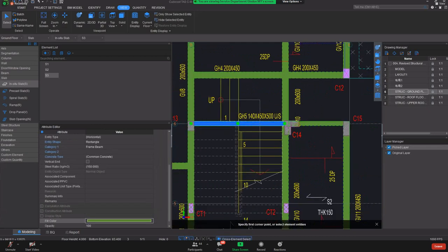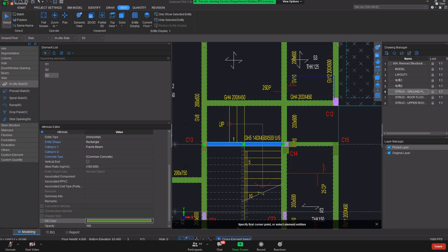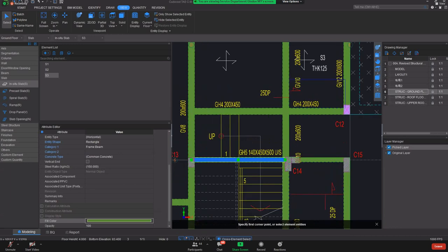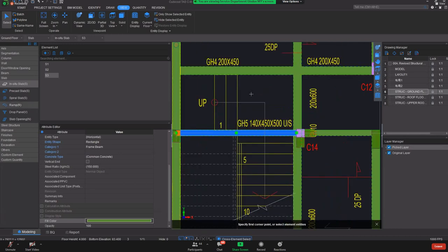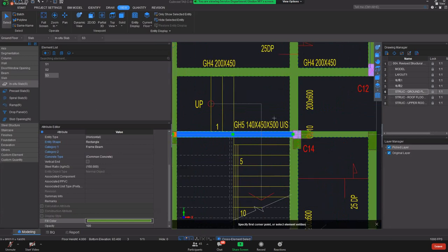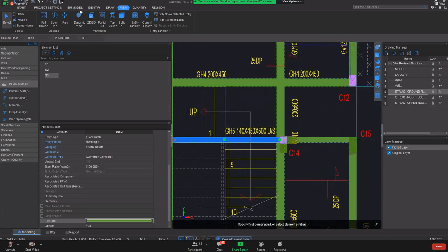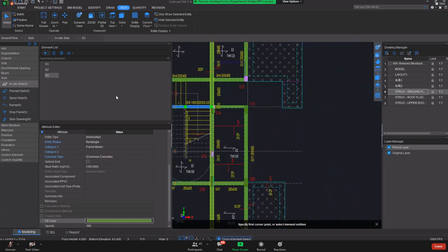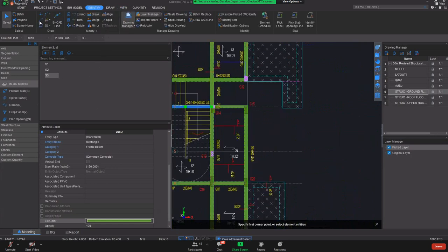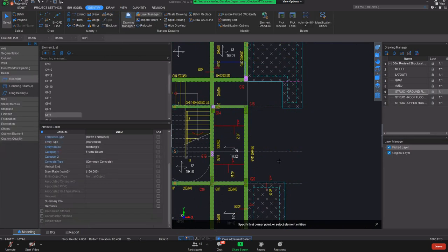If you want to make your specific beam become a specific length, if this auto identify, let's say, I do it this way. If you want to draw it, you might need to draw it manually. If you want a specific 4.5 meter length, the function is you need to open what we call dynamic input.